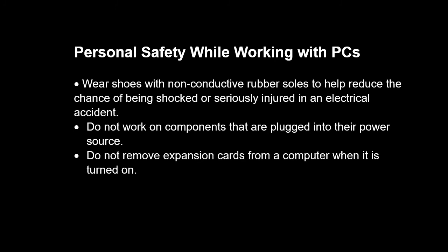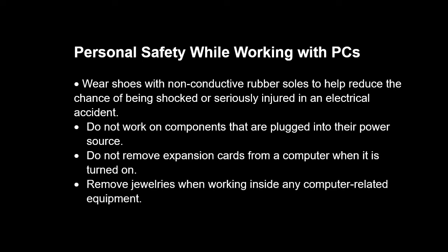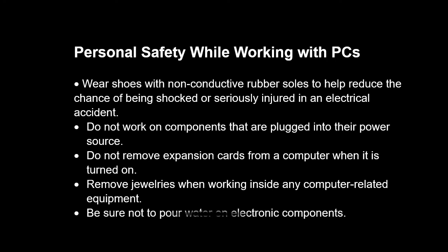Do not remove expansion cards from a computer when it is turned on. Make sure before you work with PCs, everything is turned off and unplugged. Remove jewelry when working inside any computer-related equipment because jewelry is made of metal, so it is a good conductor of electricity and will cause electrical shock or accidents. And be sure not to pour water on electric components.